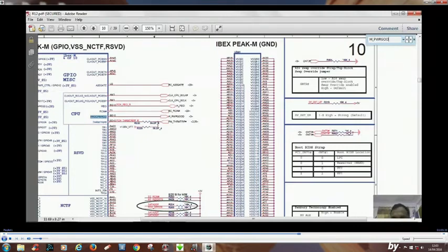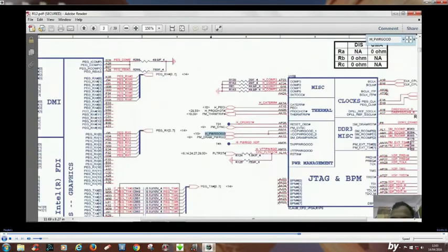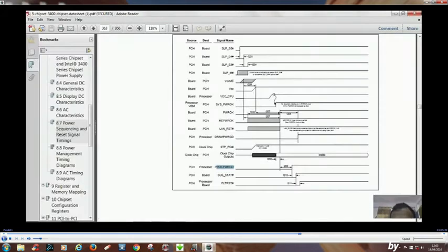You can see this H power good is going to the VCC power good 0 and VCC power good 1, and this is the final step. This is the final indication to the processor of power good, the last power good generated by the PCH.